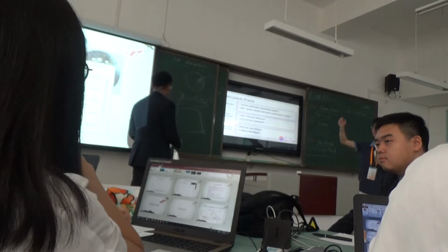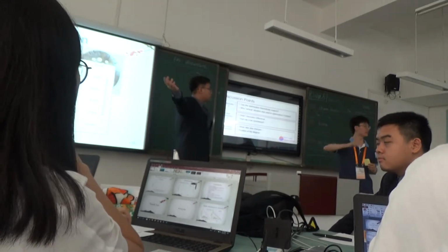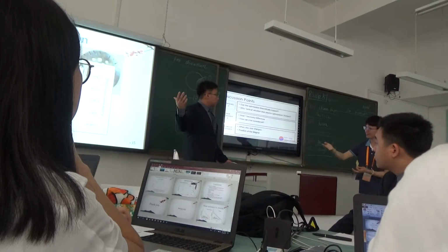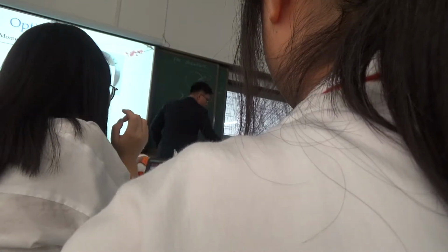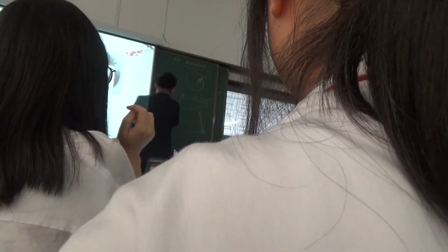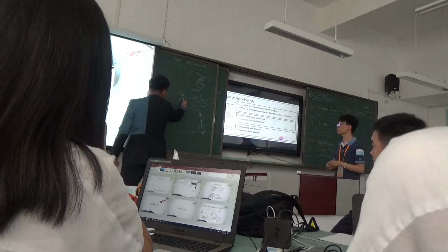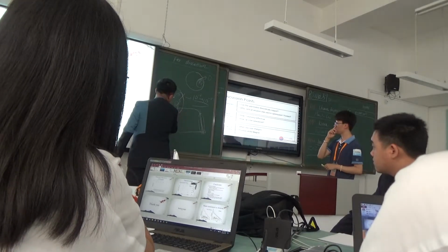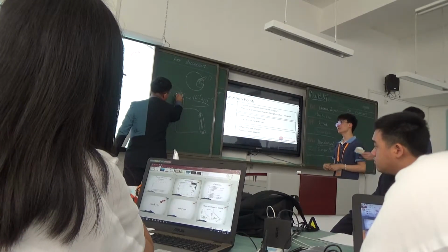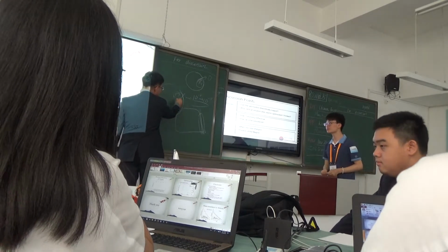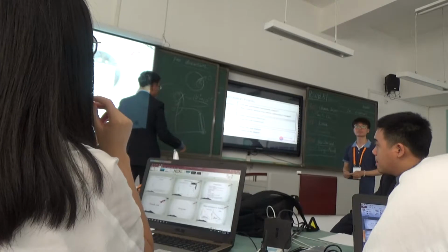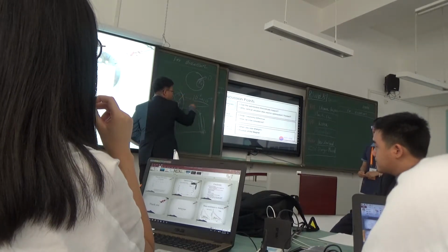I believe that if you put the hole inside here, the heat conductivity is better. What I mean is this: when we have a disk with holes inside it, when we heat it here, there's less mass to heat over here, so it will approach the desired temperature quickly.